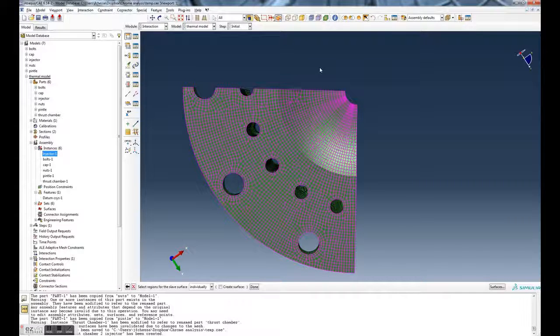Now that's very slow. The easiest thing to do is to unselect with a window. So again, keep it at individually, control, and then while you hold the control button down, use the left mouse button, and you can draw a select window, and you can see it's turning off or unselecting various elements. Now it's not really essential that you unselect everything in this window, but the more you unselect, the faster the contact search will go.